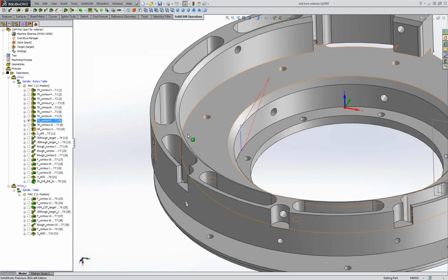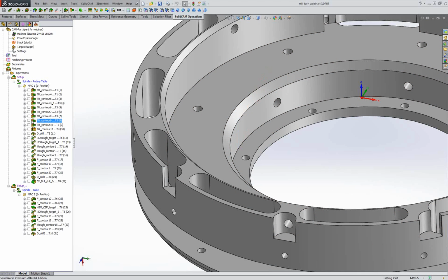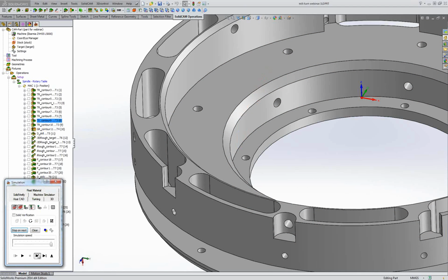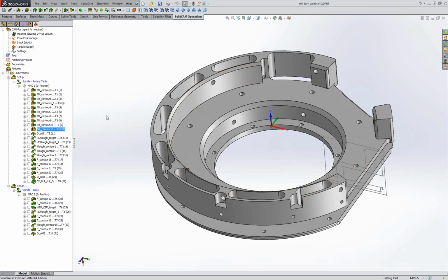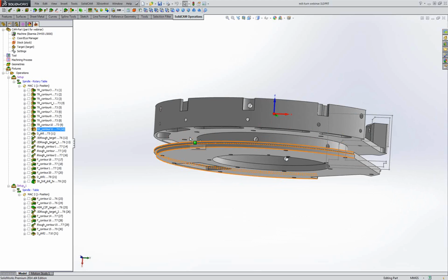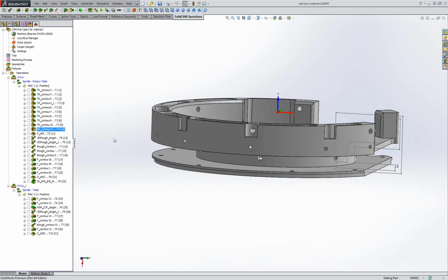The next finish operation, I will go here on this diameter down with the tool, and retract to safety. And the last one on this floor from inside outside. Again, from retract point, go direct to start of toolpath, up 1 millimeter and retract. And this way I make finish in internal part. What we have left here is this groove, a lot of material to be removed.